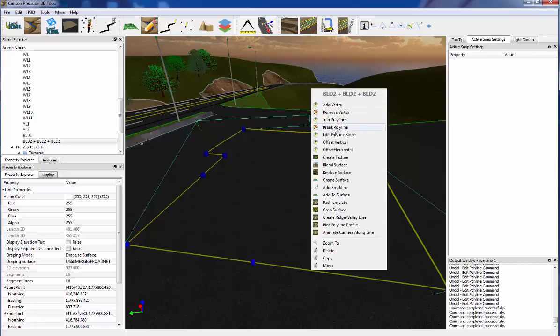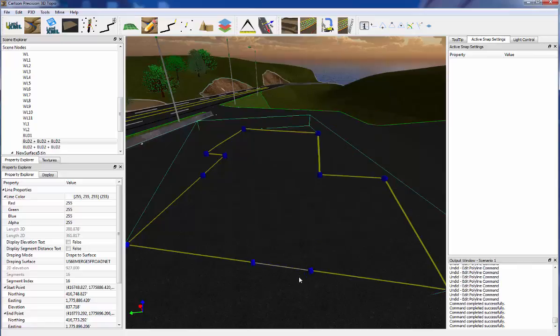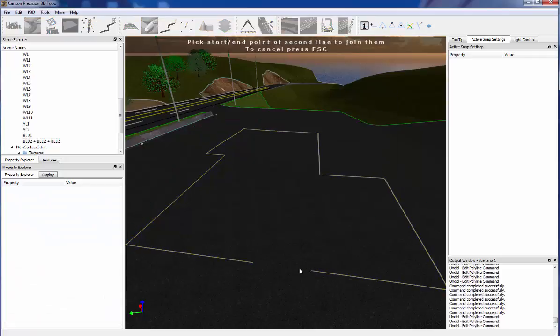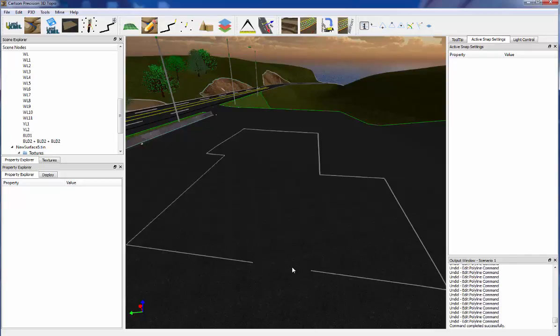And break this polyline out here. And then I'll delete that. So if I wanted to do the join command in this case, there isn't a second polyline, but it's detecting that at this point. So essentially you're wanting to close the polyline and not join it. So the logic in this particular routine is smart enough to know that.